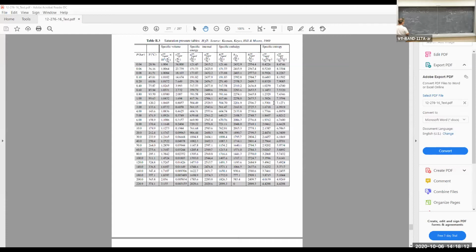So I get Q 1 to 2. What's the heat transfer? It's an adiabatic process. It's insulated, so it's 0. The heat transfer is gone. By the way, this electric work is done on the system, not by the system, so I'm going to get plus W electric from 1 to 2 is equal to delta H from 1 to 2. The boundary work term went over to the other side of the equation, and the delta U plus P delta V became delta H because it's a constant pressure process. Of course, this is equal to a mass times H2 minus H1.